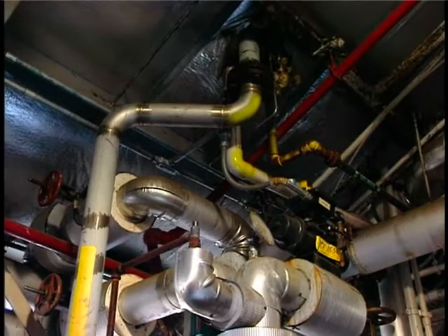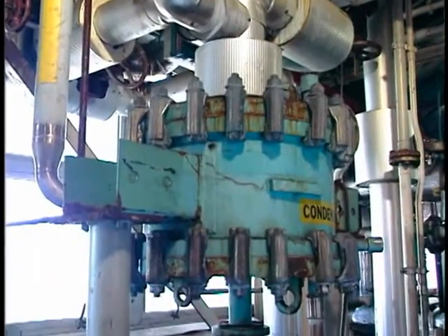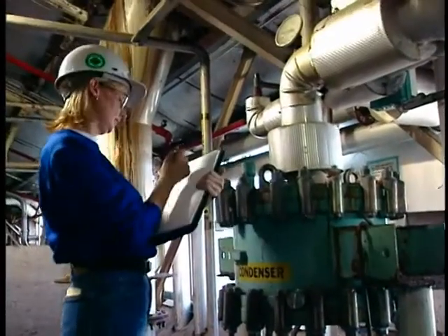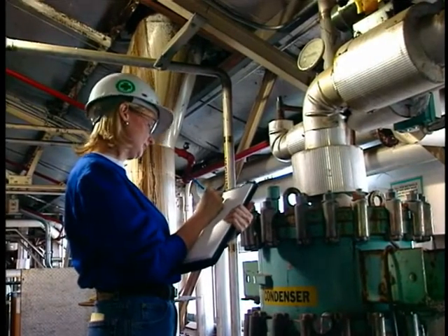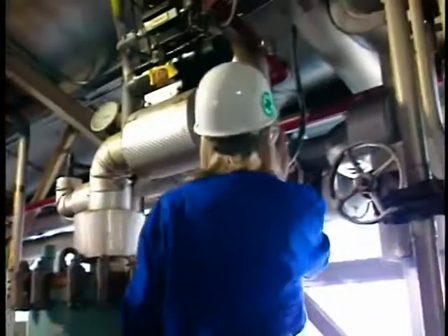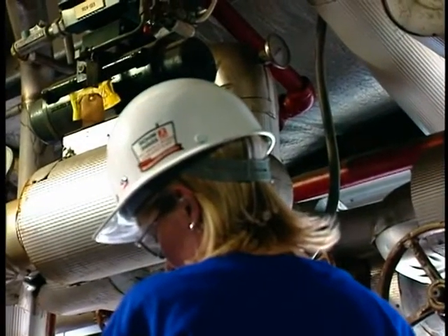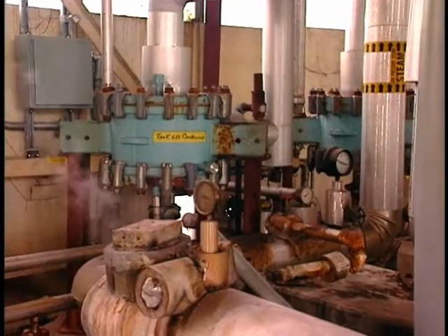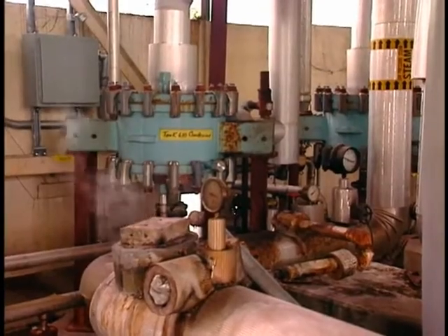The best indicator of the performance of a condensation system is the outlet gas stream temperature. Since the outlet concentration is equal to the vapor pressure at that temperature, increased outlet gas temperature would indicate reduced collection efficiency. If outlet temperature records are maintained, they should be reviewed to determine periods of increased temperature. Short-term increases are usually associated with frost removal, and the records can be used to determine the frequency.